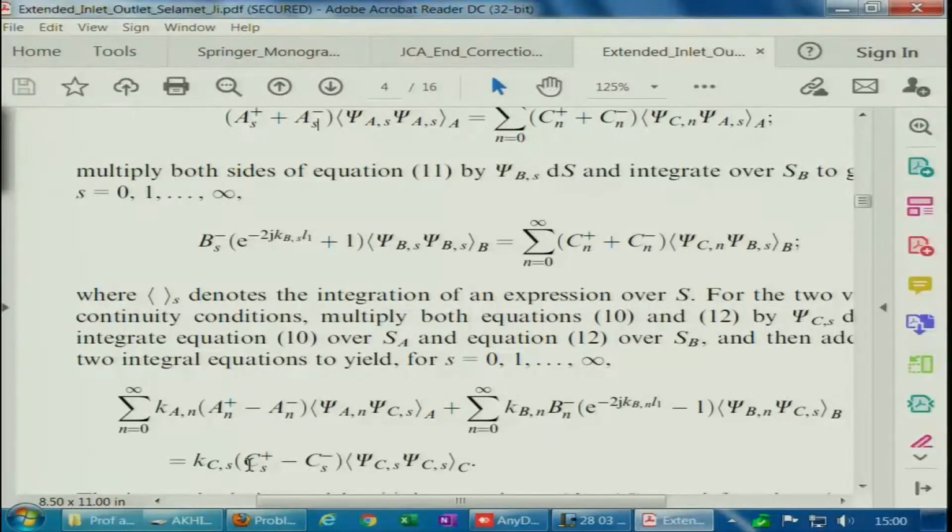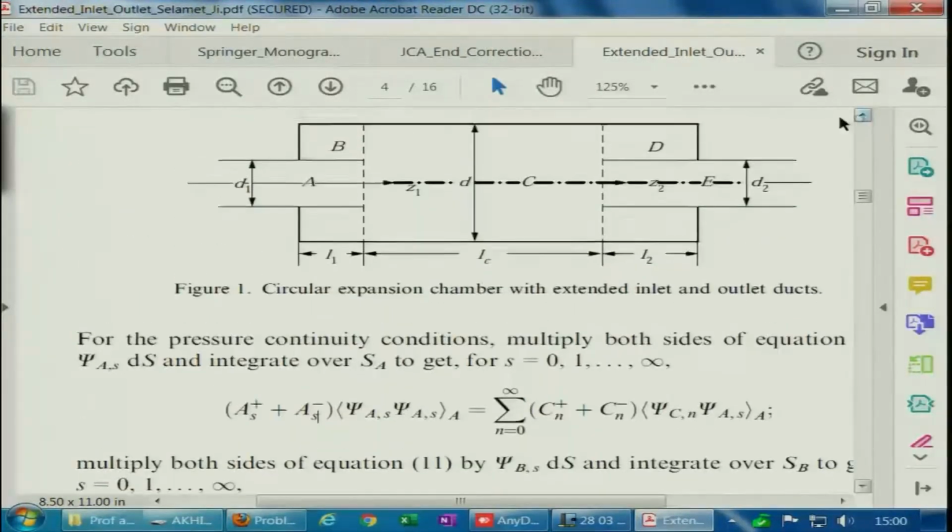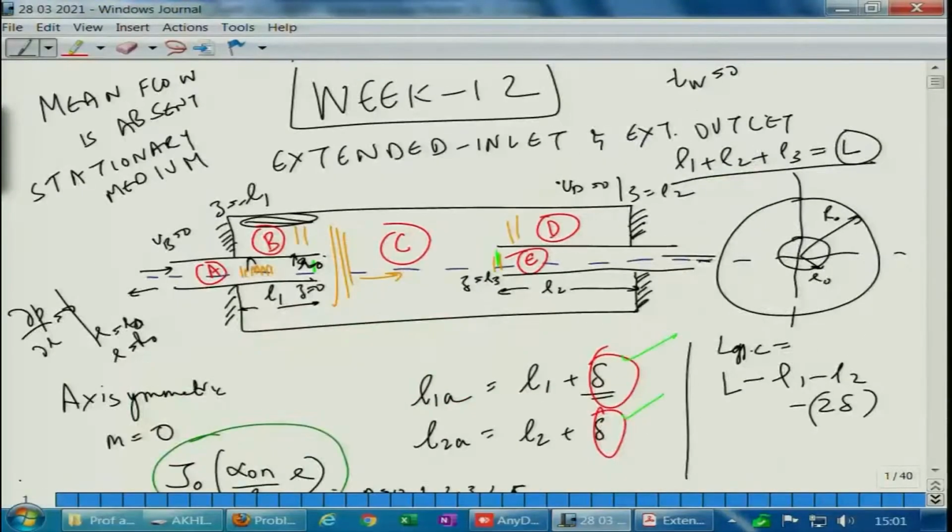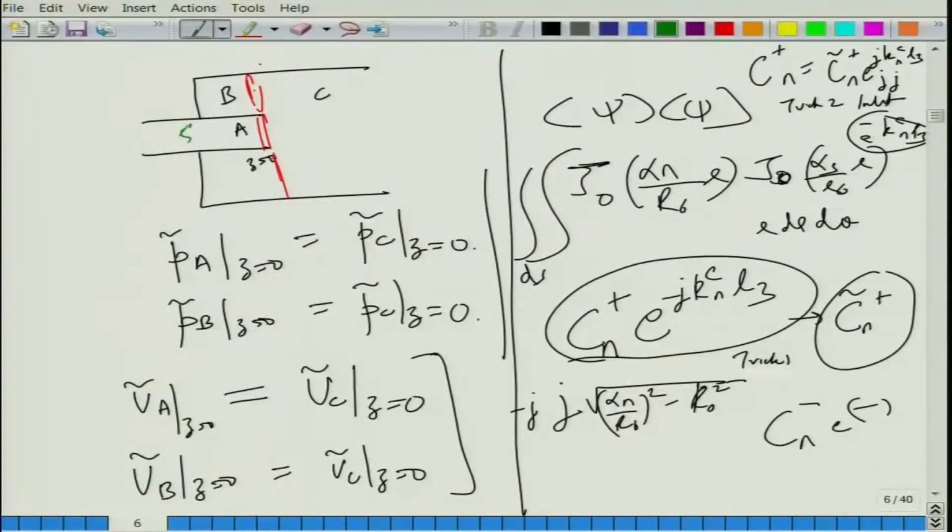We can have different numbers of constants in the chamber, in the port, and different numbers of modal summation value n in the inlet port, as well as in the cavity here or in the chamber. So, basically, if you go to the presentation, in this we can consider, say, first 5 modes here, 10 modes here, 20 modes here, or actually 10 modes here, same, this would not be too different, or you can have 10 modes here, 10, 10, 10, basically n1 modes here, n2 modes here, n3 here.